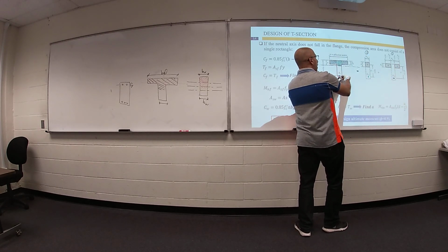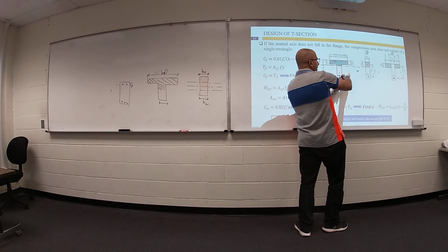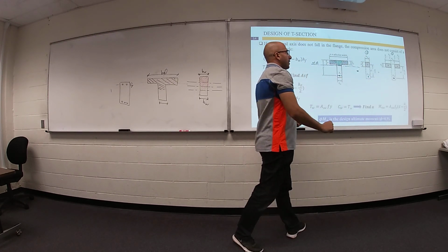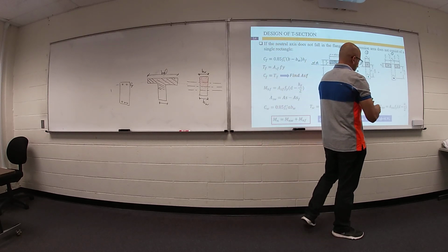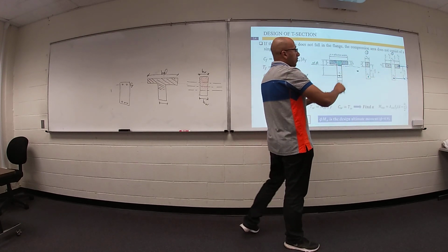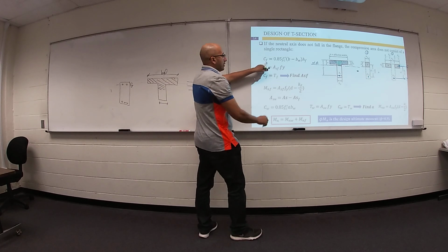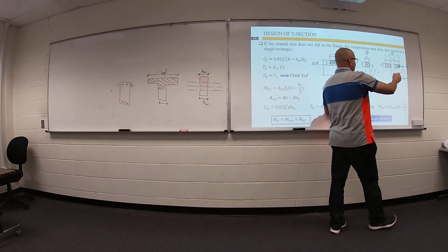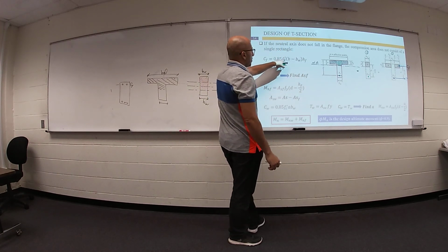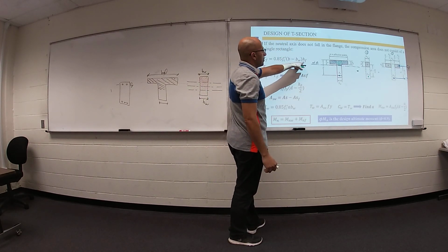The second part bears the remaining part of your area of steel with the remaining part of your area under compression. Let's talk about the first one. We have compressive force here on this area, and we have tensile force in this steel reinforcement. Both of them are equal. The compressive force, we can call it C flange, equals 0.85 f'c times (b minus b web) times h f.